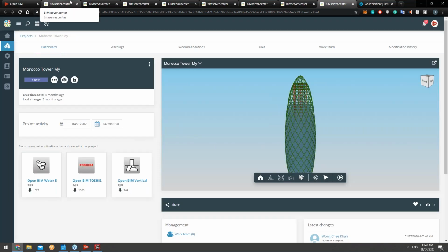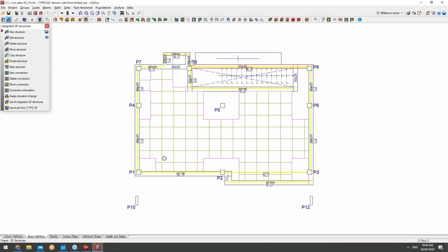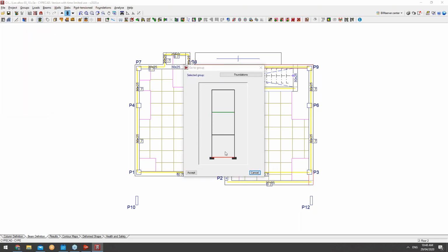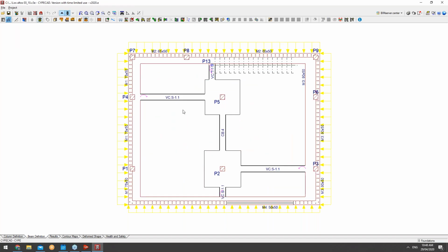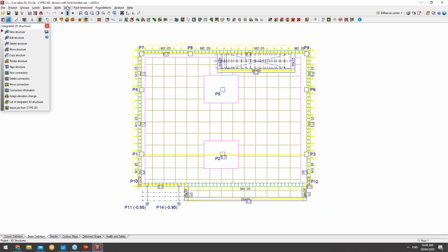Okay, so we've got a question here from Suman Polikonda. Sorry if I said your name incorrectly, I apologize. How to insert escalators in our RCC structure, please explain in software, sir. So escalators, we would have to create openings within our slab. So we can come over here to my foundation level. Oh, sorry, not that foundation, not first floor, like that. So, Suman, you'd have to introduce openings within your slab. So coming over to slab, introduce openings here.